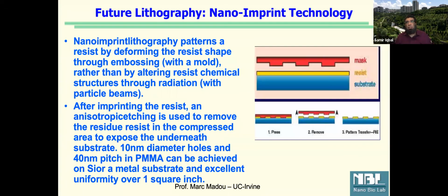This stamping concept is another thing, what you call nano imprint lithography. So instead of using just an ink, they are using a coating of hard material and they press it down with high pressure and high temperature, and they transfer the design into some polymer material. All right, questions?